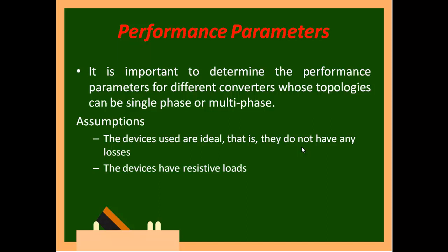Okay, we have already seen 3 pulse, 2 pulse and 6 pulse. In 3 pulse we have seen 2 types of configuration. So put together you get half 3 phase, then semi, and then full. Full is nothing but 6 pulse, the other 2 are 3 pulse, and we have seen 1 2 pulse. So totally it becomes 4 topologies we have seen till date.